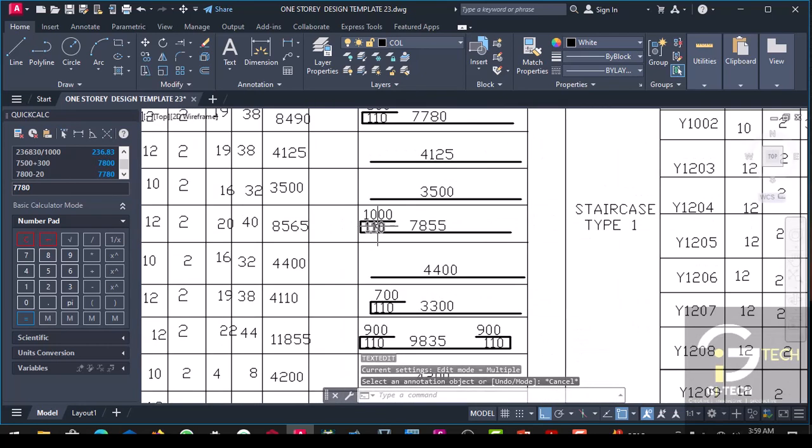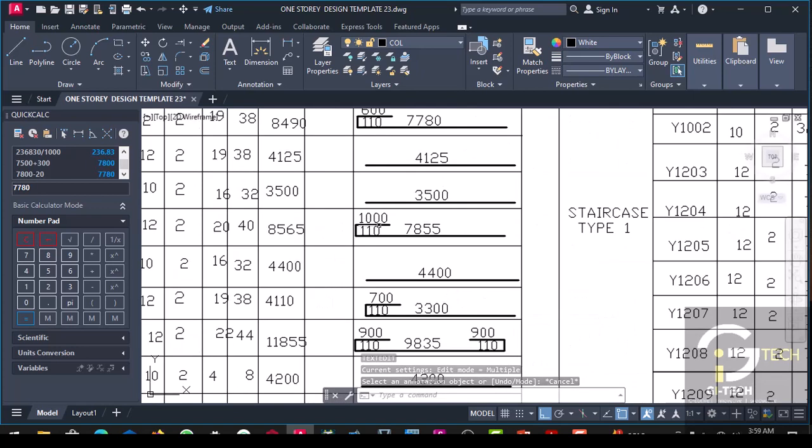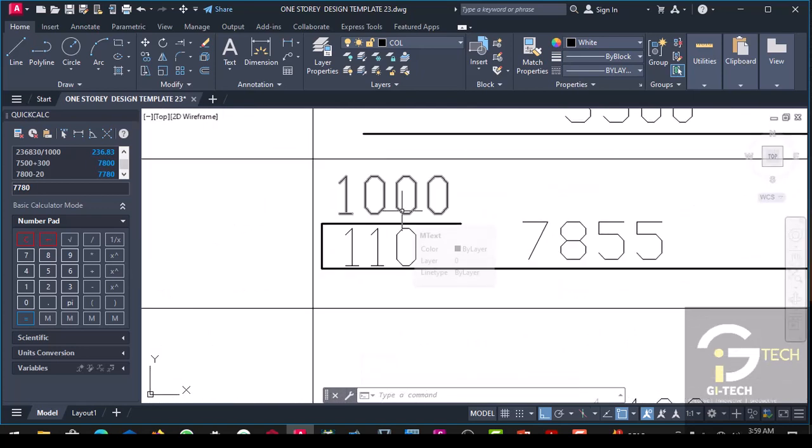Now, when you calculate the length of these returning bars using the formula 0.15L, take for instance, if it gives you like 500 or 520, you can pick something that is higher than that 520. You can pick something like 600, but the length of these returning bars should not be less than 0.15L.